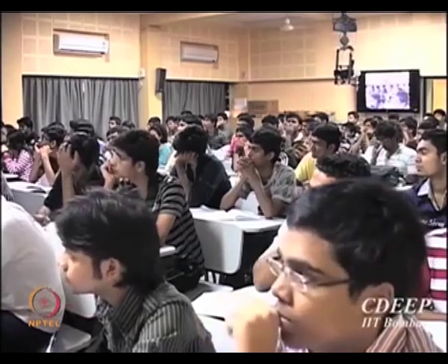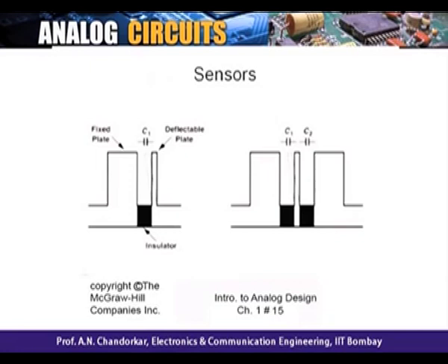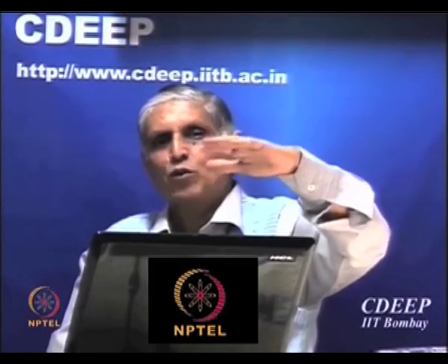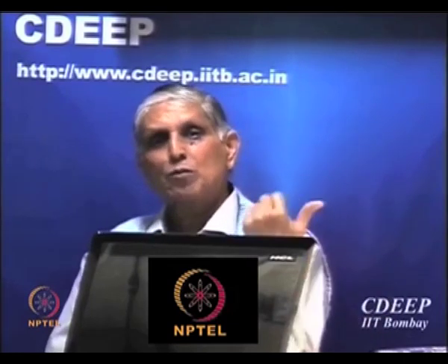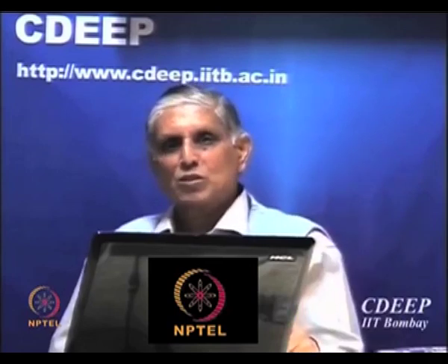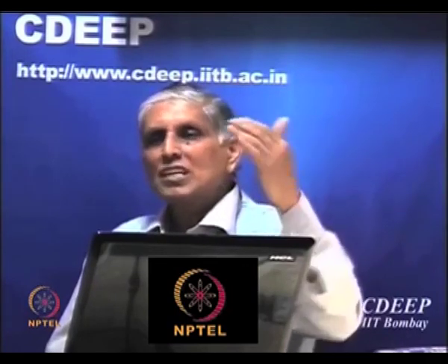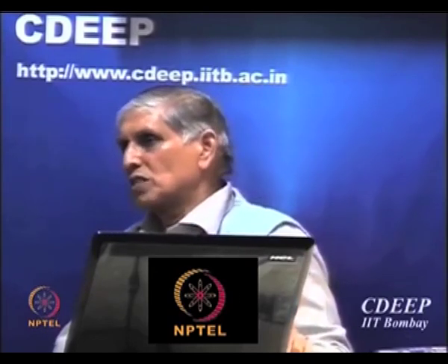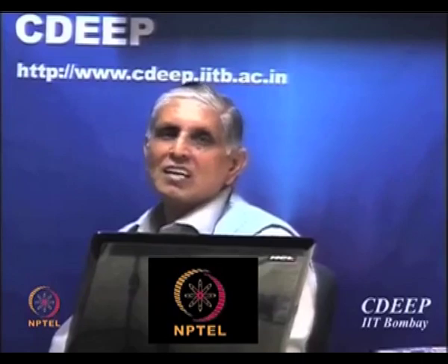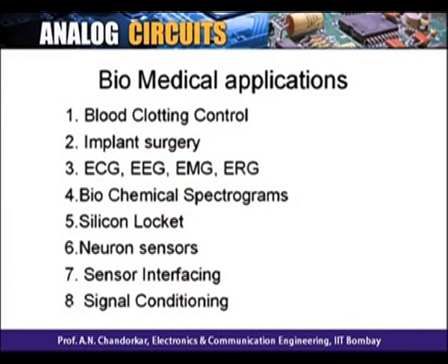So now we are looking for silicon sensors, okay, and one of these methods is to use capacitances as their measurement, because in silicon I can make a cantilever which under stress by acceleration or by force will vibrate or move down. The variation in this is proportional to the bending moment it got, which is proportional to the force it was sensing. And the change here can be monitored as a capacitance. If I have two plates here, if it comes closer, capacitance is larger. If it goes away, capacitance is smaller. The change in capacitance is the measure of the force or the acceleration. Okay. This is one more area which requires a lot of analog digital processing, which is MEMS.